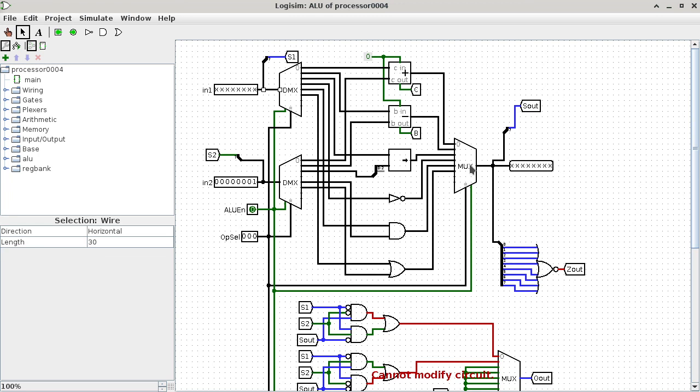The gray dot, or the wire or the port right under the gray dot, is the selection. It is 3 bits wide in this case, so you can specify a value from 0,0,0 all the way up to 1,1,1, which designates which of the input pins, input 0, input 1, all the way to input 7, connects to the output. Now, what about the other wire? What about this wire that is extra?